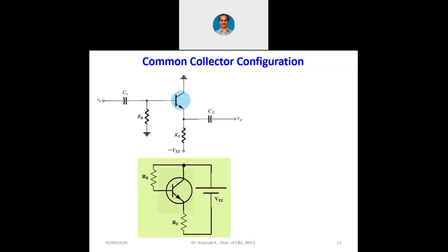The depth of the ocean also can be measured with the same reference. So it does not mean that the ground level is 0 level. It is only a reference for measurement. Same way, in our circuitry, whenever we put ground symbol, it does not mean that it is 0 volts. But in general, we keep on mentioning ground as 0 volts, because with respect to that, we measure all other voltages.